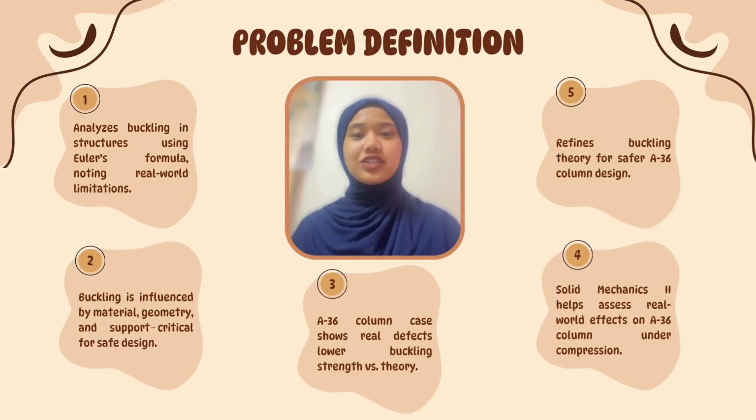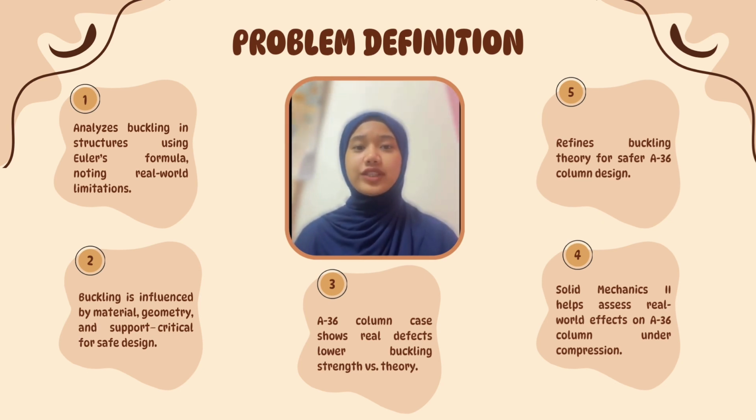The project addresses structural instability in mechanical and civil engineering structures caused by buckling under compressive load. Euler's formula is used to determine the critical buckling load in the steel rod problem, but these assumptions do not accurately represent real-world structural elements. Buckling behavior is influenced by factors like the material's modulus of elasticity, the member's effective length, moment of inertia, cross-sectional area, and end fixity. Understanding these influences is crucial for ensuring reliability and safety in design applications.